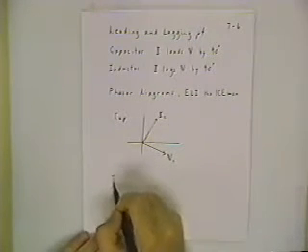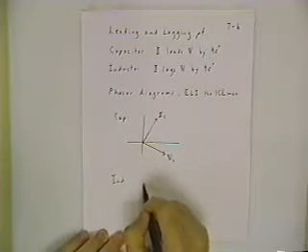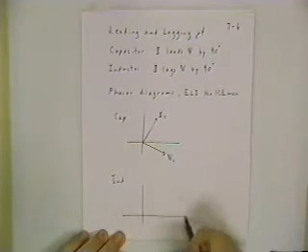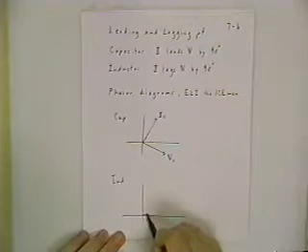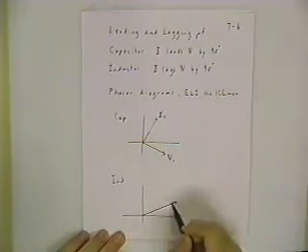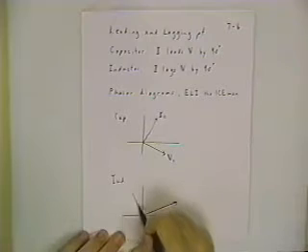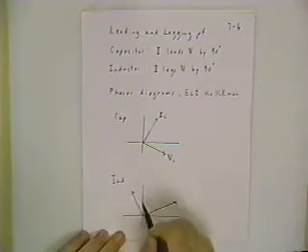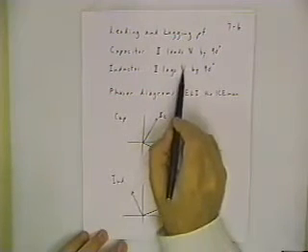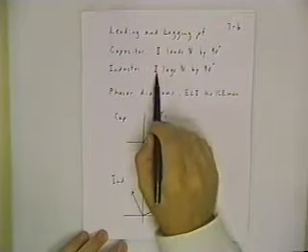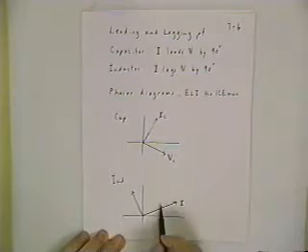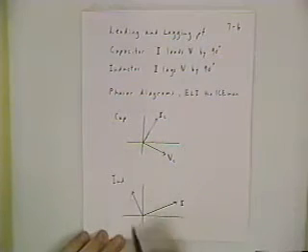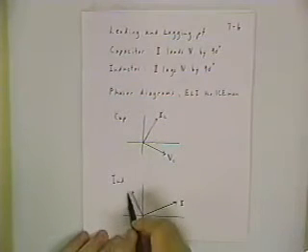Okay, for an inductor, it's very similar, that we're going to have a current lagging behind the voltage, or you can turn that phrase around and say voltage leads current, or current lags voltage. It's just a matter of keeping track of who passes a certain point first as you're rotating around counterclockwise.